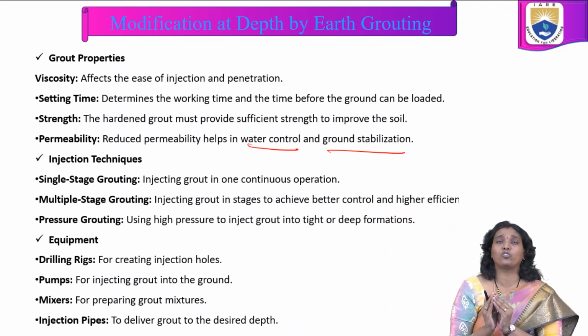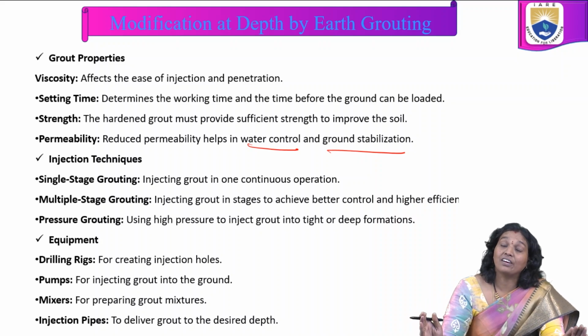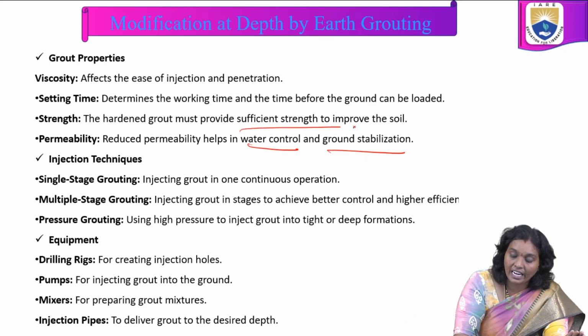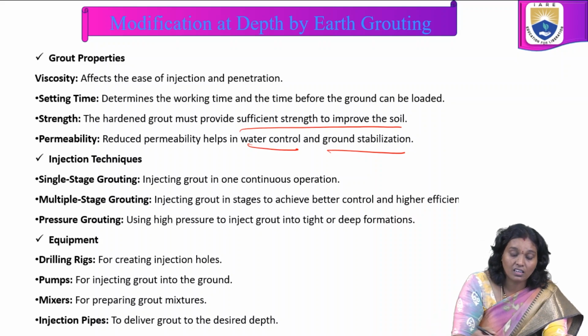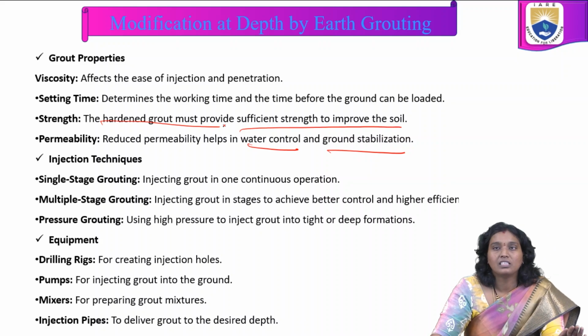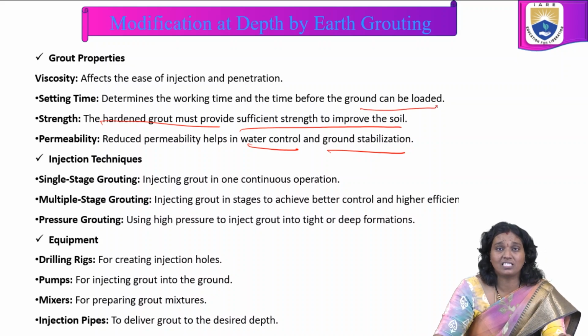We are concerned about the required strength. From that point of view, we have to get the required or sufficient strength to improve the soil. The hardened grout must provide that in such cases. Coming to the setting time, it determines the working time and the time before the ground can be loaded. Like this, we have to understand the various grout properties.